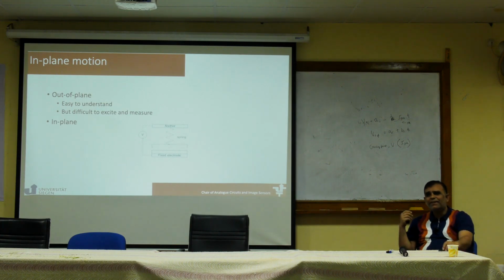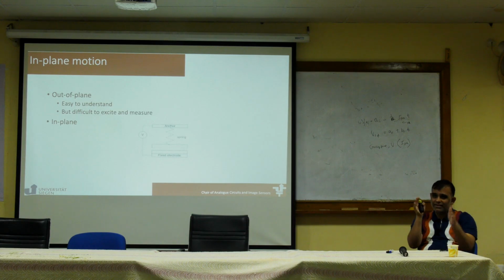Now, electrostatic force is a kind of weak force. It's not a very strong force compared to other mechanical forces. So often a single parallel plate finds it very difficult to provide enough excitation, particularly when we are making small resonators. Remember, with our parallel plates, everything is quite small.